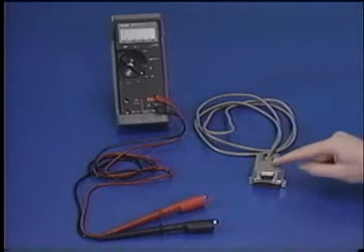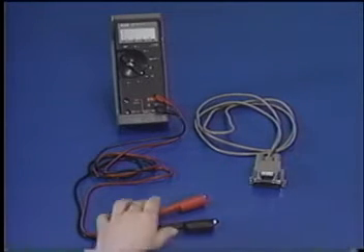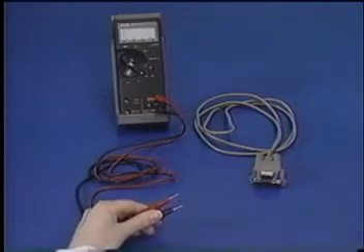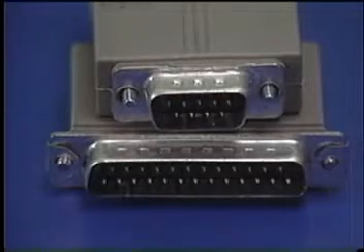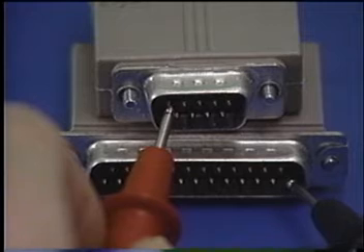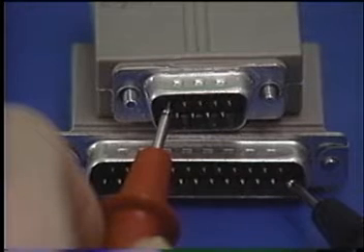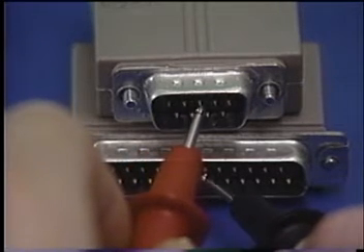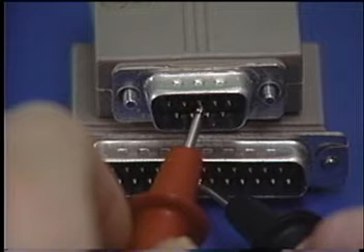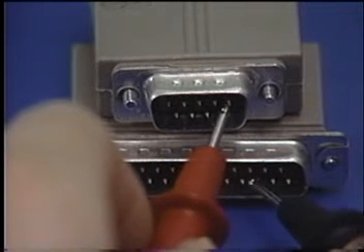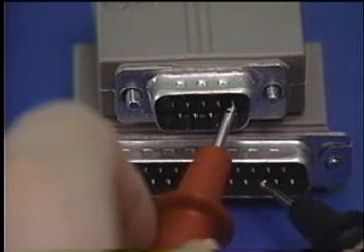Multiple conductor cables can also be tested in a similar fashion. Remove the alligator clips and touch each pin on the connectors. The continuity check allows you to locate both ends of a conductor or to find broken conductors. All of the conductors in this cable are providing continuity from one end to the other.